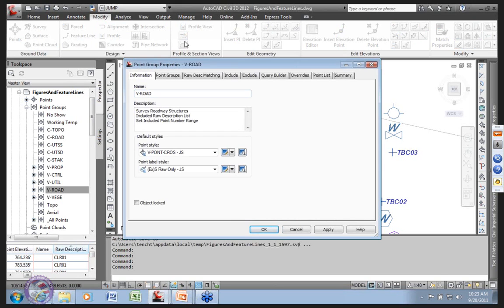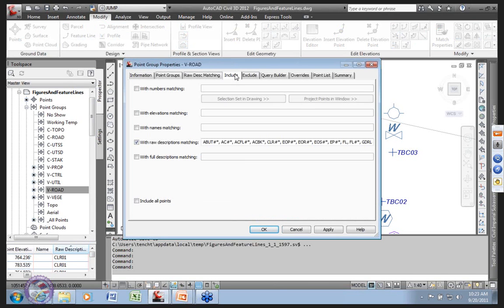And this is related to the keys, this idea of the description matching and grouping them all together. They're kind of an interrelated process, and you'll notice the syntax that we employ, right? So we're looking for certain line codes. Okay, anything with a pound sign says I'm looking for something with numbers in it, and I'm looking for anything after that number. So you can do some fairly sophisticated matching rules in your raw descriptions.